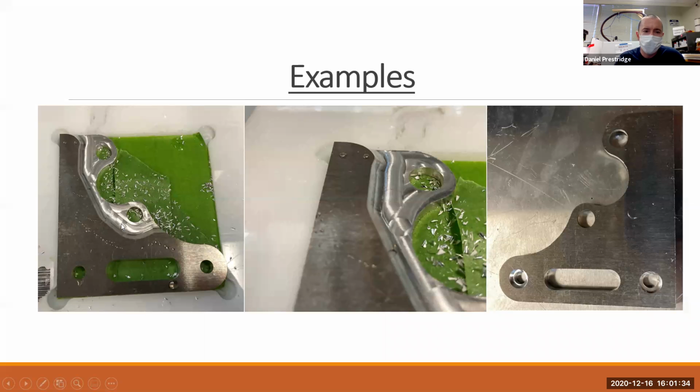So we did the same thing with this, except if we had taken the same idea with the last one and said, okay, we're going to cut this part, we're going to put it down, we got our 0. Well, if we did that and we just cut with the end mill all the way around, even if it's small, use the smallest cutter you can find, it's still going to have a really small radius at the edge.